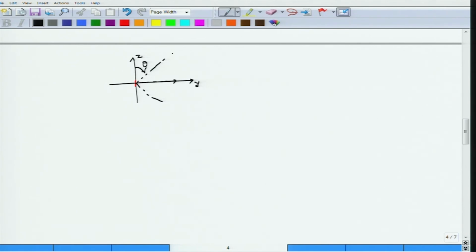Then for this theta, let us assume that it is 45 degrees, we mark a point. Along the y axis, where theta is equal to 90 degrees, you mark a point which would correspond to the maximum length. Then along this line you cut the corresponding sin 45 degrees, because we are trying to plot the magnitude pattern. So, you find what sin 45 degrees is, take its magnitude and cut that particular distance. Whatever the distance that is mentioned in this blue line is actually this sin 45 degree magnitude.